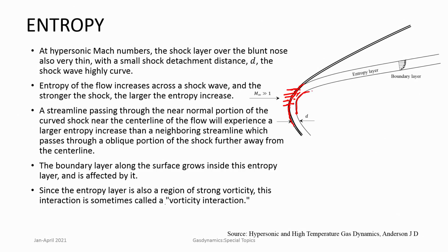Now, a normal approach that is usually carried out for the analysis of these kinds of vehicles, or any aerodynamic analysis, is to split the flow field into parts where we do not have to consider viscous effects, the inviscid part, and the part very close to the body where we say that viscous effects are important, which is the boundary layer.